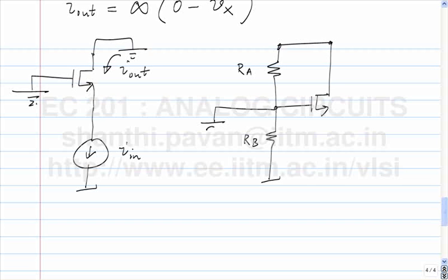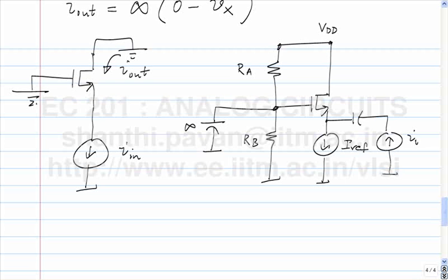Put an infinite capacitor between gate and ground. This is IREF. And this is VDD, alright. So somebody suggests a capacitor and then a current source, an incremental current source IN. But then I realized that if I had a current source of IN, anything in series with the current source hardly matters, so I can remove the capacitor and inject current right away.